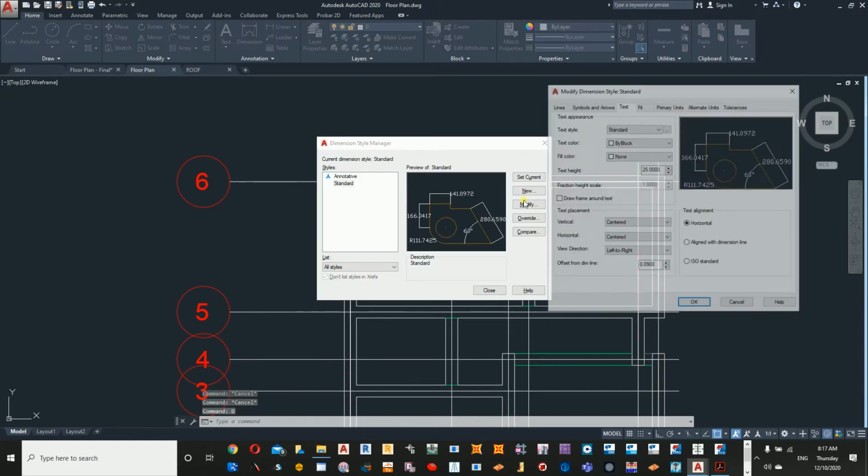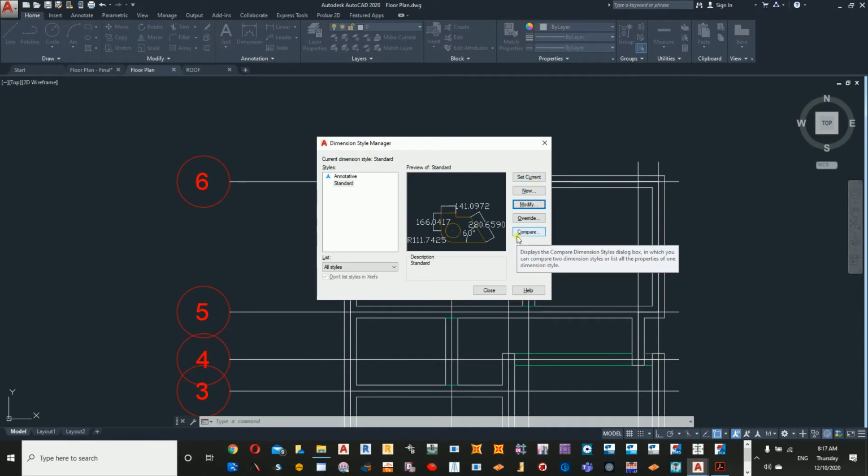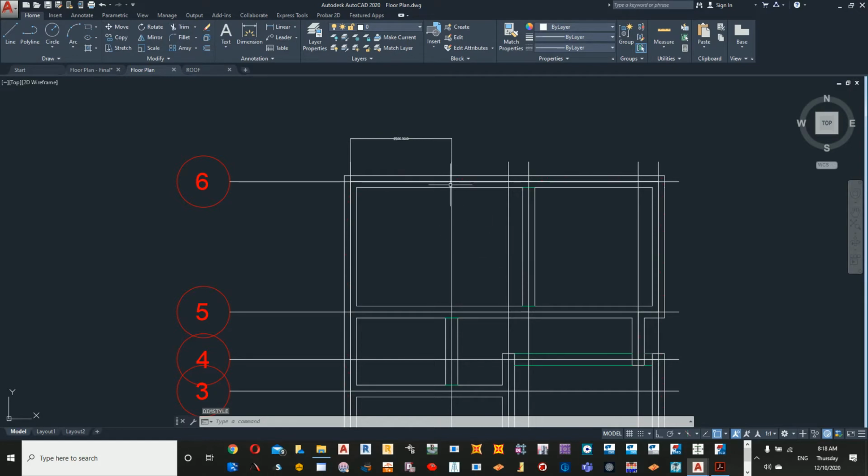Okay. And once again, I don't want to take a lot of time in terms of drawing. I just wanted to highlight if we have a drawing with different grids, what to do. So when you try to draw a Revit or any structural project, try to take all the positioning of walls, because sometimes you will be having an intermediate beam or a secondary beam in the middle. Drawing a secondary beam is going to be a little bit hard if you are not drawing the grid line from the beginning. Okay, so it's always better to know the lines from the beginning, and then accordingly to put the beams.